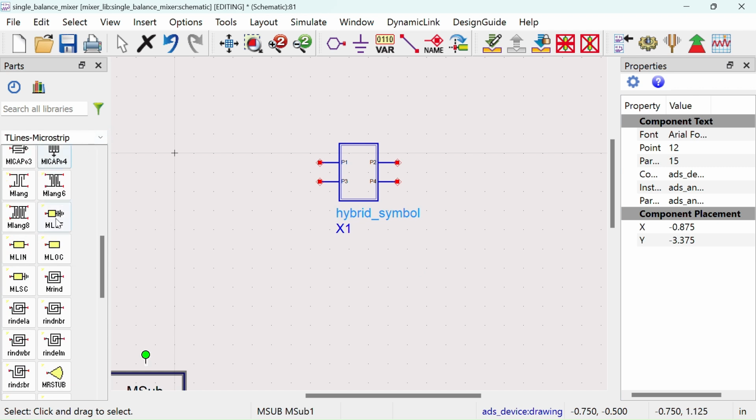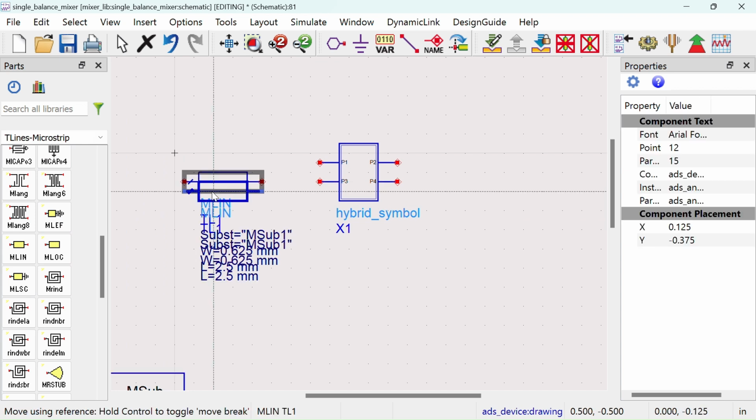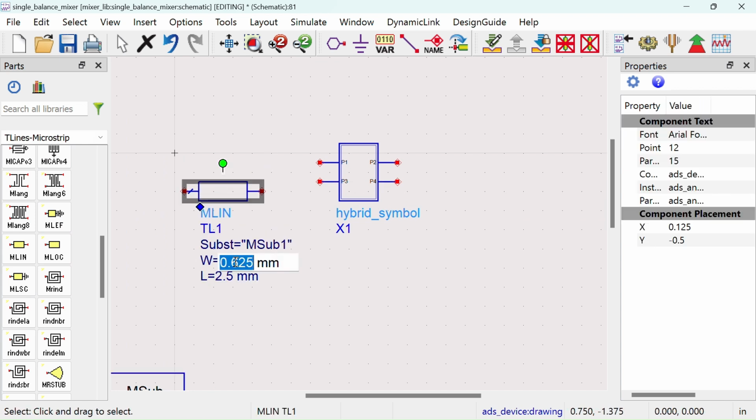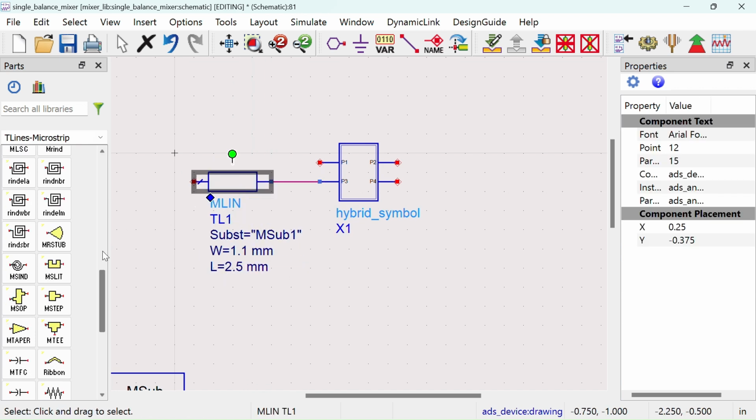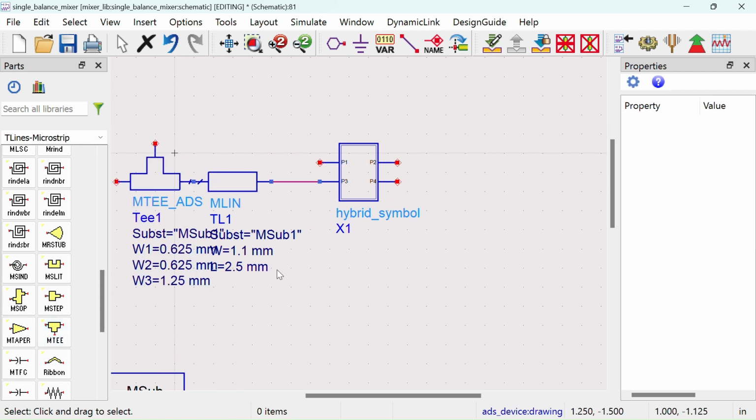This design is based on two Schottky diodes. A Schottky diode is a commonly chosen nonlinear component for mixer circuits due to its ability to combine input signals and generate new frequencies through its nonlinear behavior. This property enables it to produce the sum and difference frequencies needed for frequency conversion in mixers.